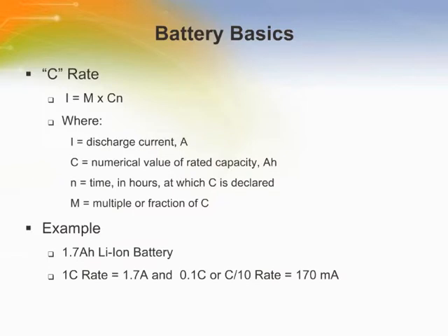When charging or discharging, the rate of a charge or discharge is often expressed in relation to the capacity of the battery. This rate is known as the C rate. The C rate equates to a charge or discharge current and is defined on this page. A battery discharging at a C rate of 1 will deliver its nominal rated capacity in 1 hour. Typical maximum rate of charge for a lithium battery is 1 C.